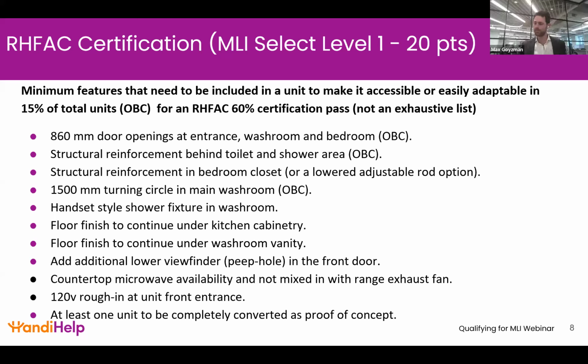It makes it quite challenging. So we're getting some questions like, does the bedroom also need to have a turning radius? With respect to the washroom there, I believe the answer is if it's on another level, no, it's just on the main level, right? Bedrooms will need to have a turning circle if they're part of the 15% barrier-free units. Bedrooms do not need the turning circle if they're part of the visitable units.